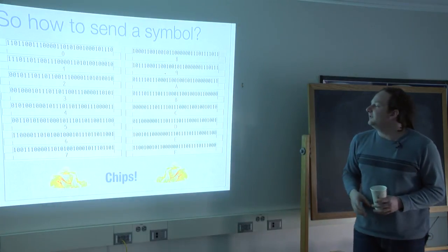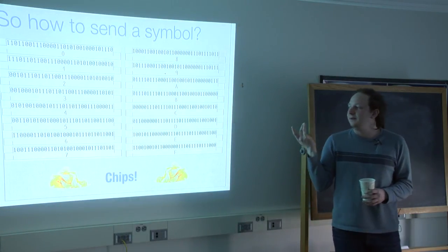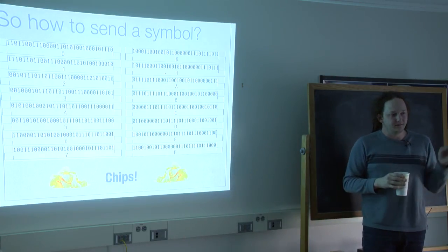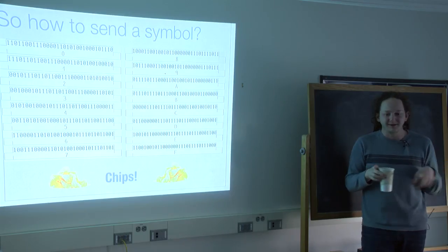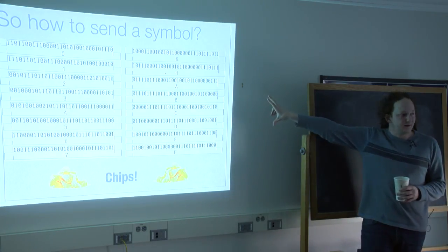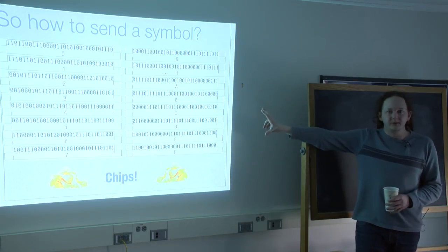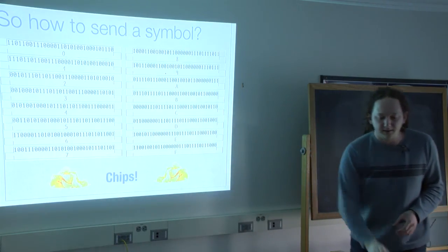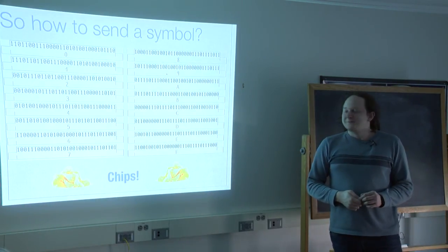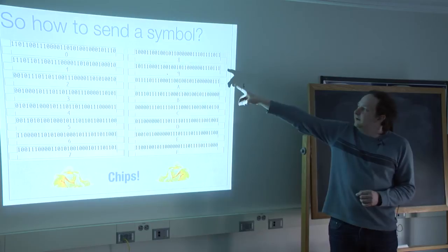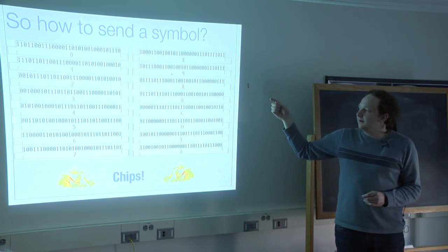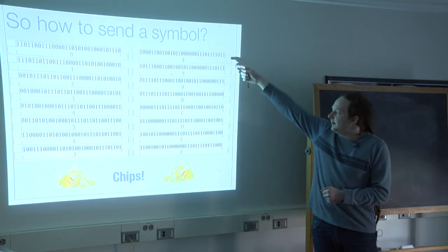So I told you that the symbols were nibbles wide, that 0 was 32 chips long, but I didn't explain what those chips were. So this is the complete set of chips for 802.15.4. This comes from a papercraft game that we made. So, each one of these, you have symbols for 0, symbols for 1, all the way up to 7, and again for 8 to F.